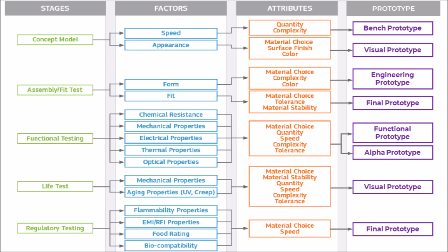Assembly and fit testing. This stage is about making some or all of the parts for an assembly, putting them together and seeing if they fit properly. At the gross level, this checks for design errors. And at the fine level, this is a matter of minor dimensional differences and tolerances. Obviously, any test involving tolerances need to use the actual manufacturing process or one which has similar tolerances. So, any engineering prototype or production prototype is required.